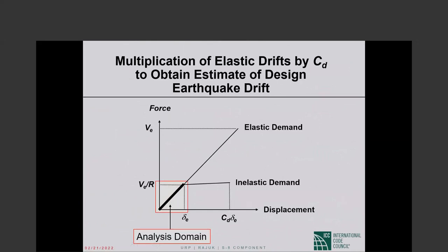Now, a variation of this picture I have shown you many times: the load deflection curve of a particular structure subjected to the design earthquake of BNBC 2020. If the response were elastic, the total force developed in the structure would be capital V sub E, and the total displacement, not shown here, we called lowercase delta sub capital E on an earlier occasion. Anyway, today the important thing is that we are designing for V sub E divided by R. That's our design base shear.